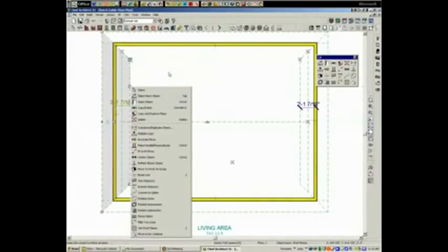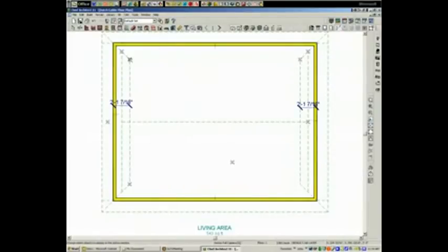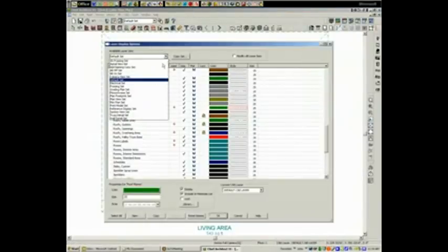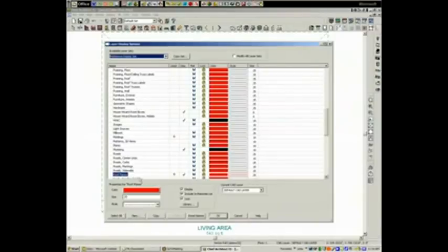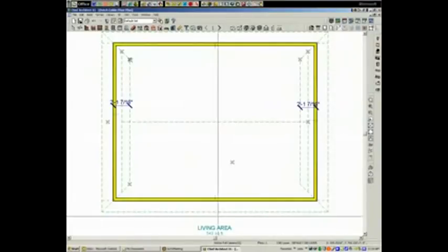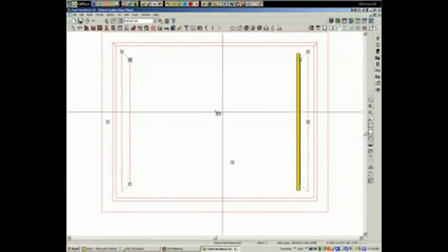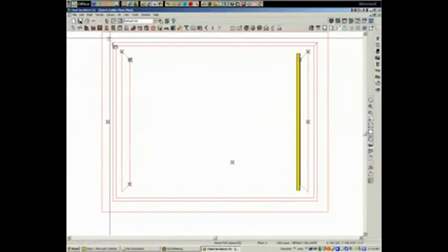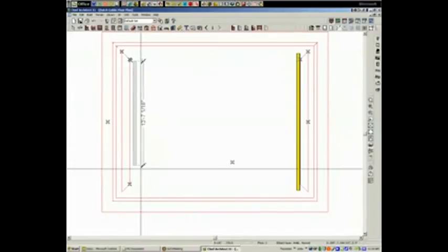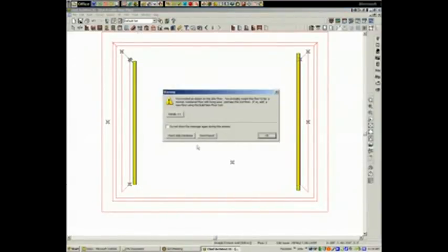I need roof planes to be referenced, so I'm going to go over to the reference set, and make sure roof planes are referenced, since they're not by default in the reference display set, so I got that set. Now I can go up to the attic and turn on the reference display. There's that line that I'm looking for, that roof line. We'll draw a wall up here.